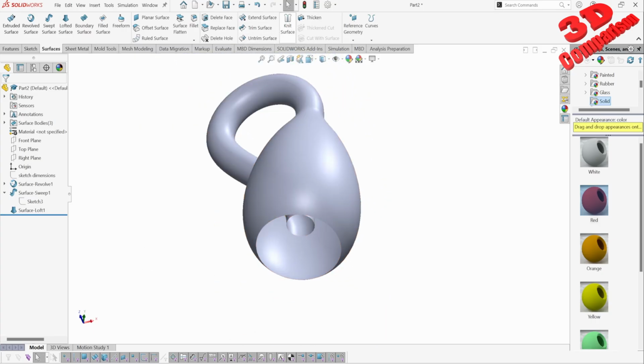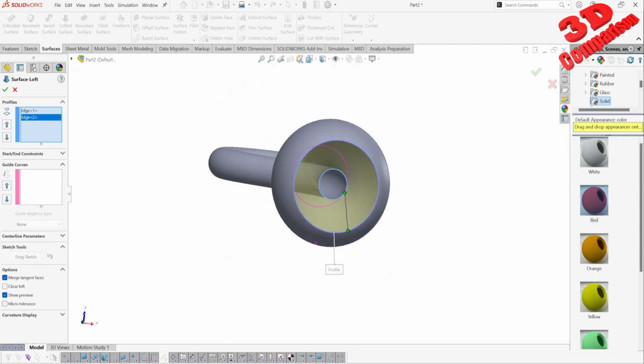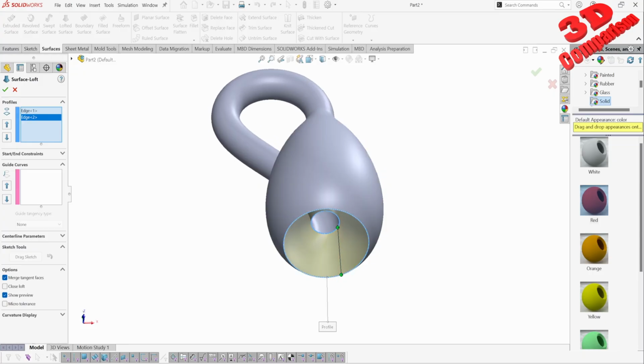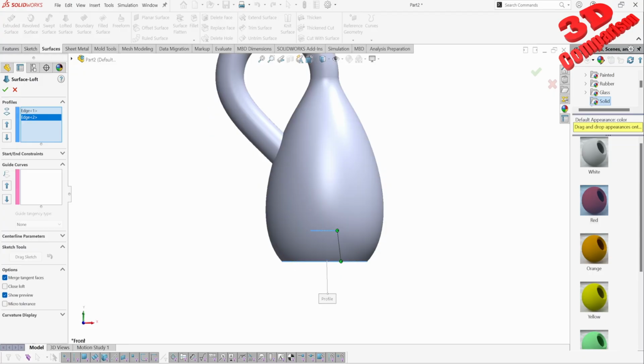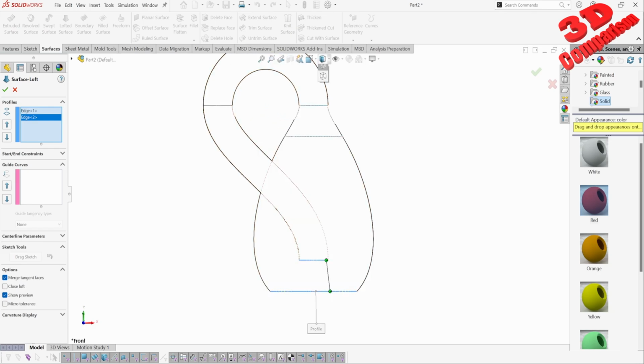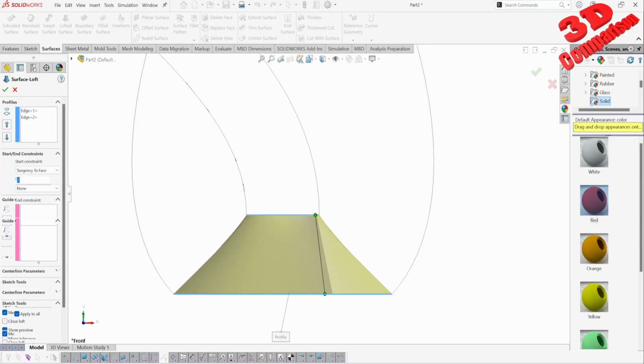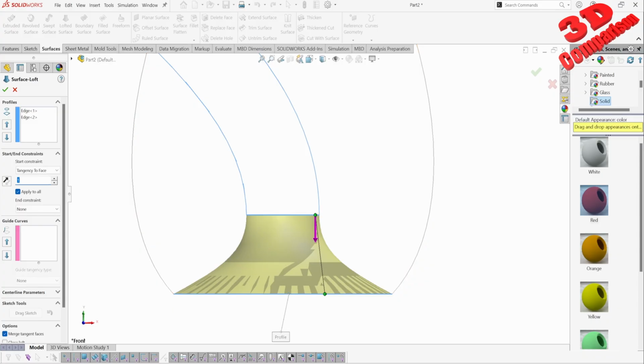So if I rotate, I can do the same loft. The main problem, if I click on those, is that I don't really see the preview of this, since it's not that visible. To better visualize this, I'm going to click over here in order to go to the front view. And now I will swap the visualization to have the inner. So this will be the last one, wireframe, and this will give me that preview. And we need to add that tangency over here as well. So within start and end constraints, I will add the first tangency. So those two surfaces will be well defined.